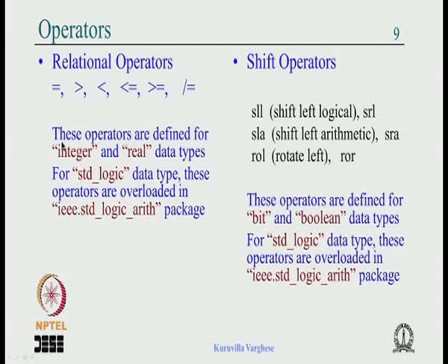Once again, internally these are defined for integer and real. For the standard logic data type, these operators are overloaded in the package called IEEE.std_logic_arith. Okay, so in principle, if you use three packages like IEEE std_logic_1164, IEEE std_logic_unsigned, and IEEE std_logic_arith, you can do many things with the standard operators. At least you can work with the standard logic data type, so keep that in mind.